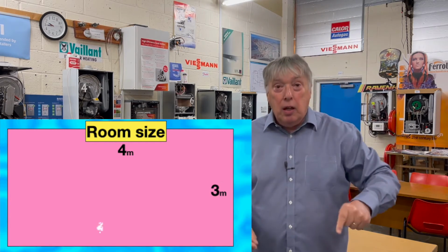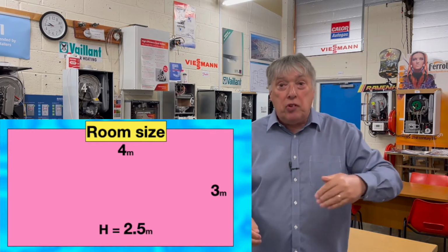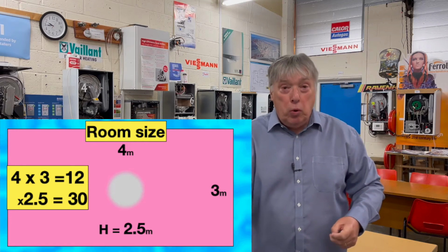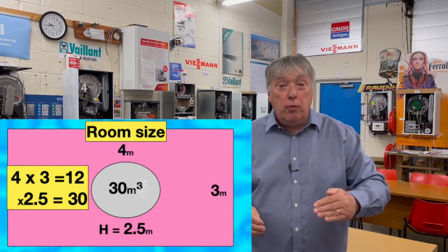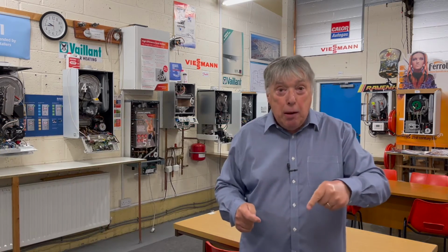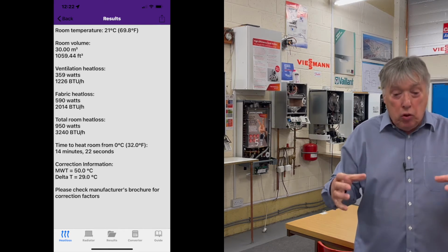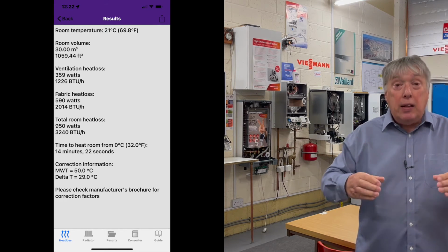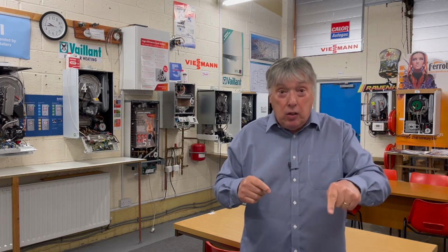Put it in and then add the temperature of the boiler flows, whether it's an outside wall or a side wall or a window. All those very easy to input figures go into the app, and as you can see here, there's the answer. It tells you you need a radiator at least this size, and depending how far the boiler is from that radiator, you may have to make it a little bit larger.